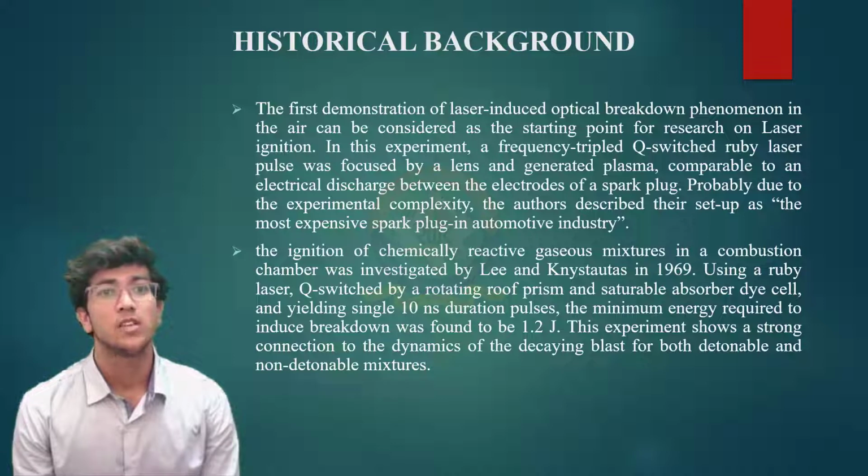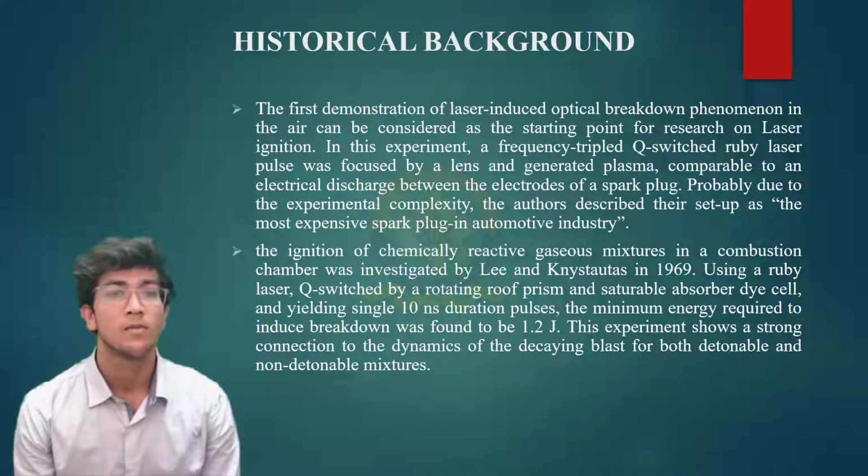The second experiment was done by Lee and Aristotle in 1969, in which the ignition of a chemically reactive gas mixture was done in a combustion chamber using a UV laser Q-switched by a rotating roof prism and saturable absorber dye cell, yielding single 10 nanosecond duration pulses. The minimum energy required to induce breakdown was found to be 1.2 joules. This experiment shows a strong connection to the dynamics of the decaying gas for both detonable and non-detonable mixtures.